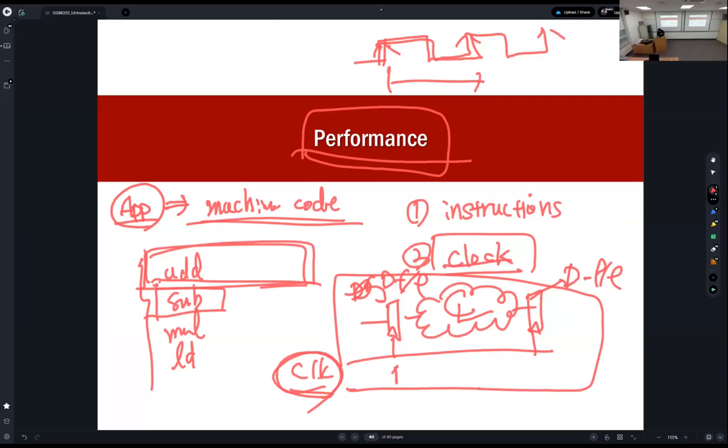At the rising edge of the clock, a signal is given to the input of the combinational logic, and after some delay, the combinational logic generates the output. This output signal is sampled by the next edge, the next rising edge of the clock signal. This is the basic operation of the system.